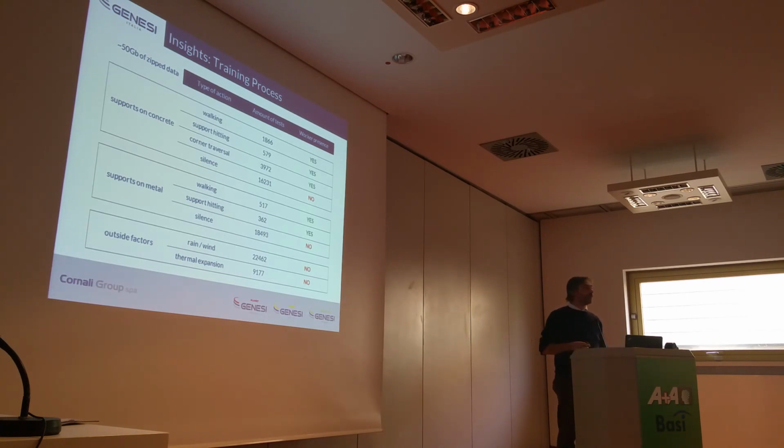I said to you before that the accelerometer captures the data 800 times per second. Each unit of this test has a duration of on average 10 seconds, 20 seconds. So you can imagine that each one of these is 10,000, 20,000 measures. And so this is the reason for the huge data set we collect.